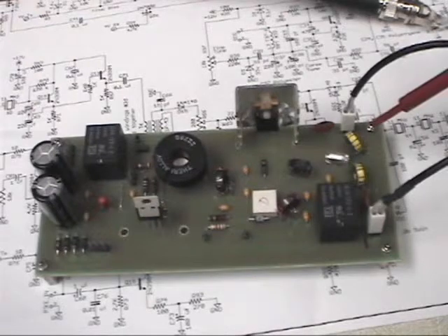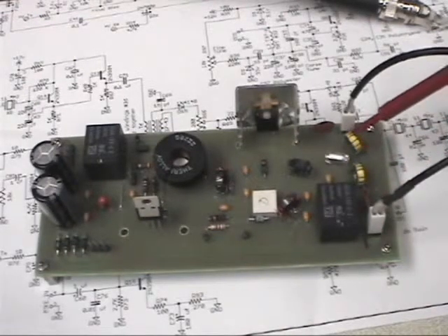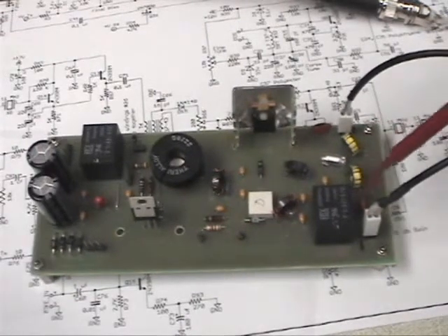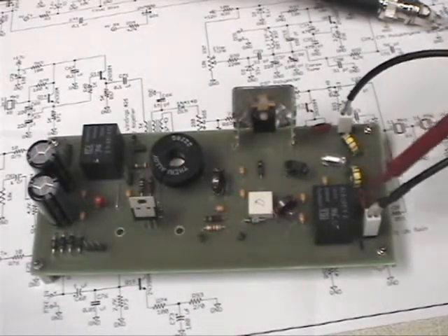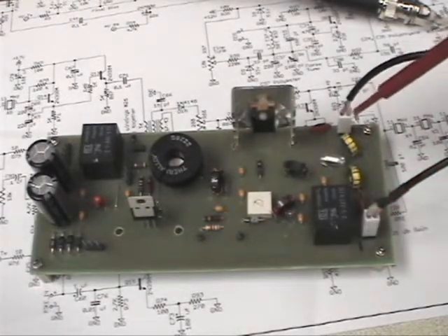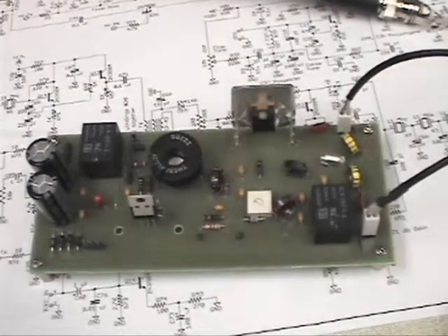I've connected the output low pass filter on a version 3 linear amplifier board. So between the coils here and the capacitors, that makes up our filter, and this is the output and an input here. So what we'll do is take a look at that on the screen and see how that looks. Here we're running a full sweep from 1 megahertz on this side to 110 megahertz on this side.